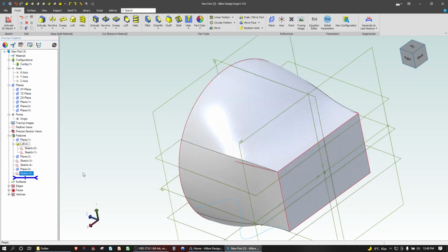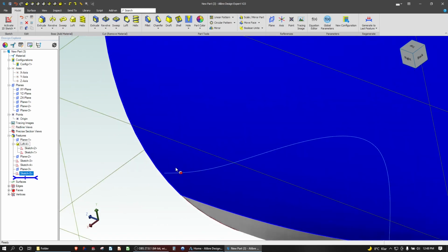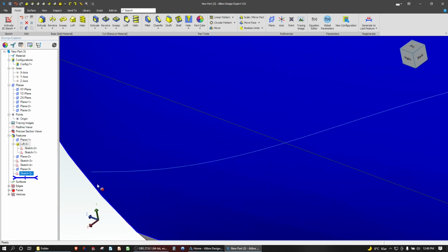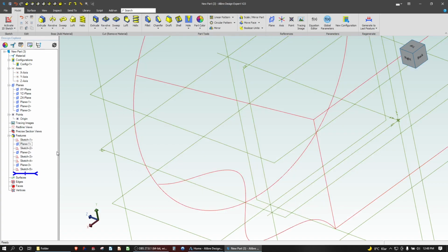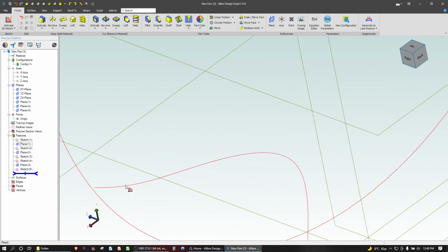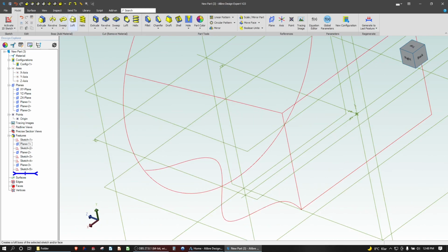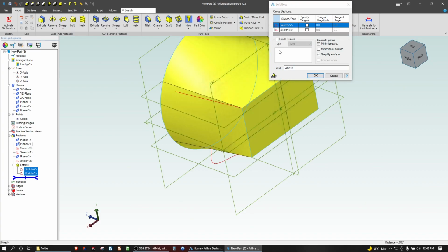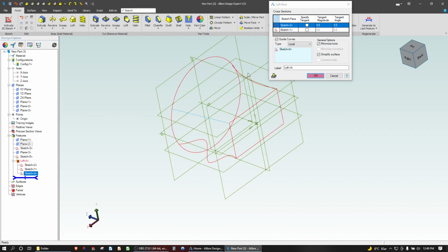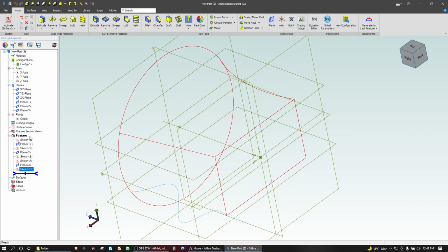And I don't know if you can tell, right? They're not intersecting the edge of the circle because it's larger. So will it work if we loft it the way it is with our guide curves that don't actually intersect the circle? We'll find out by saying loft from, say, here to here. We'll choose a guide curve. The line is our simplest one, and the whole thing breaks. So, one more experiment.